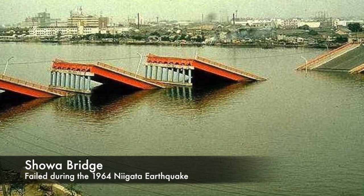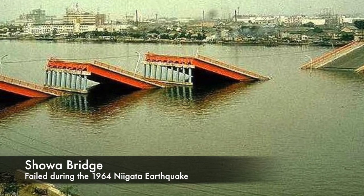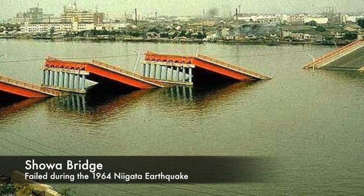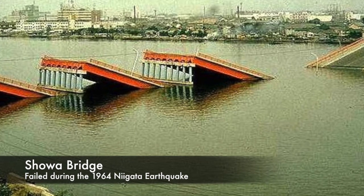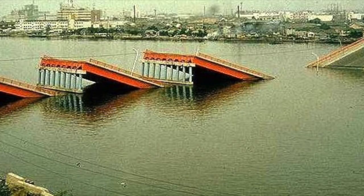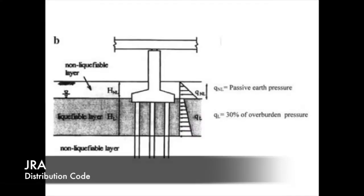Physical modeling has been developed into the main tool used to study lateral spreading. However, they are not time efficient nor always necessary. Physical models include shake table tests, centrifuge tests, and full-scale field tests. Numerical methods have been developed to analyze pile response to liquefaction. However, most are very sophisticated and require knowledge and understanding of very specific data inputs. Because of the complexity, certain codes have been developed to bypass the analysis aspect in order to design piles.